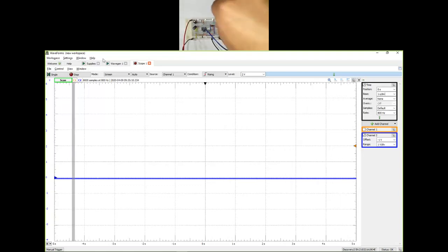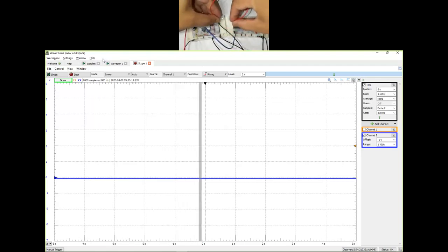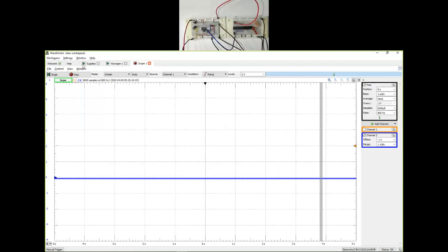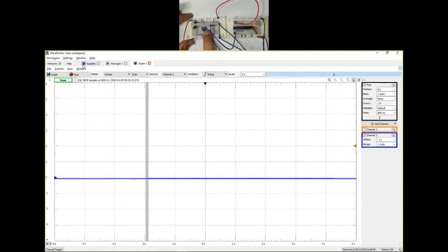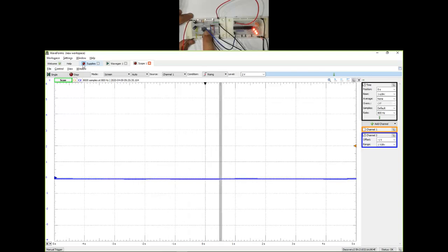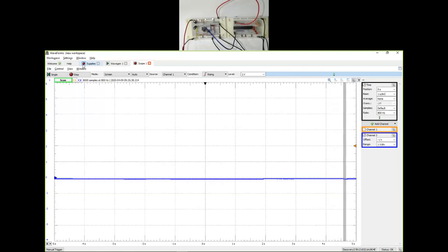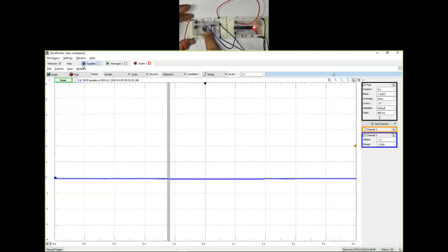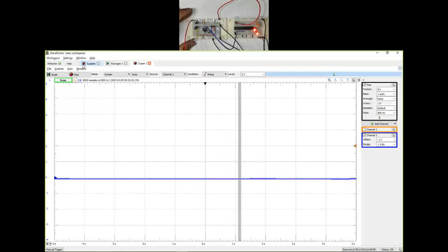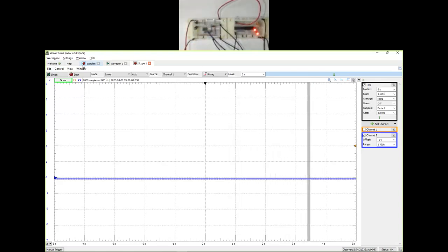Switch on the supplies again. And 0, 1, 2, 3, 4, 5, 6, 7, 8, 9, 10, 11, 12, 13, 14, 15. Now I hope you saw the entire sequence where it never gave me that issue. Earlier it was jumping up a few presses, but now it's never doing that because we have gone to 2 microfarad. So we are staying on, instead of for 100 milliseconds, for 200 milliseconds. Because we have doubled that on state, that's why it is not going down.